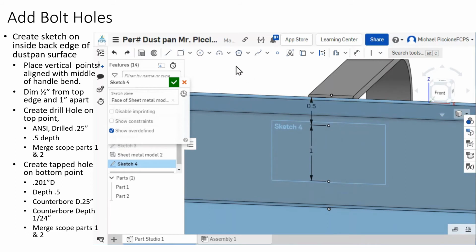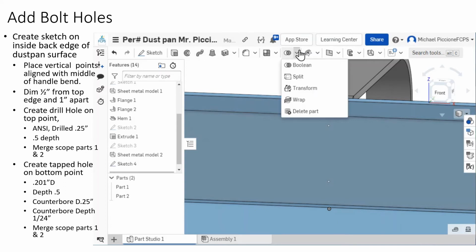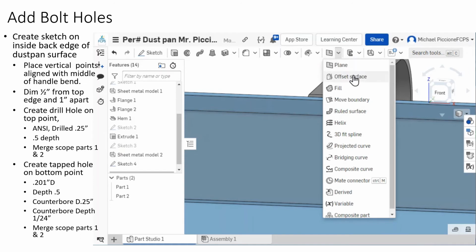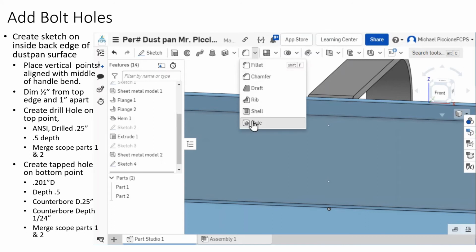So now we're going to use the hole tool after we exit our sketch. You could have drawn circles on those spots and extrude, cut, remove. One circle I want to be the same all the way through, and one circle I don't, because we're going to learn a different technique in class using our tools. There's the hole tool.